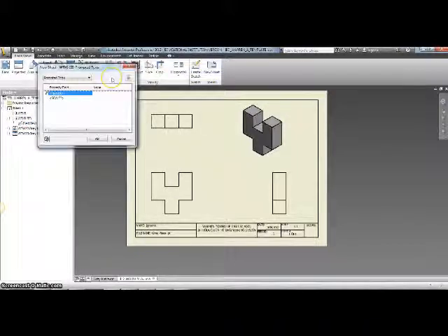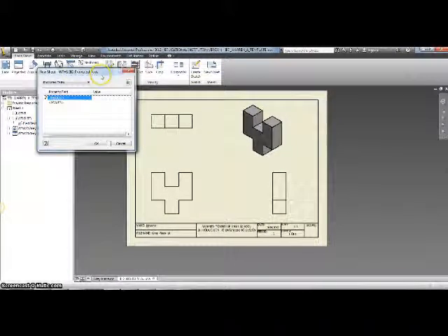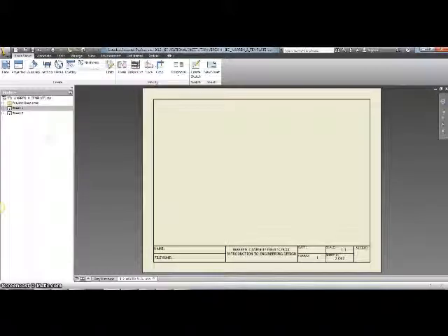When we select New Sheet, a New Sheet prompt text shows up. Well, we used period 1 before, so we'll use that. And the scale, we technically don't know the scale, but we know that for the puzzle cube, 1:1 works really well for every piece, so we're going to select 1:1, and we're going to make sure our scale is 1:1. As we select OK, you can see now that there are 2 sheets in our browser bar.